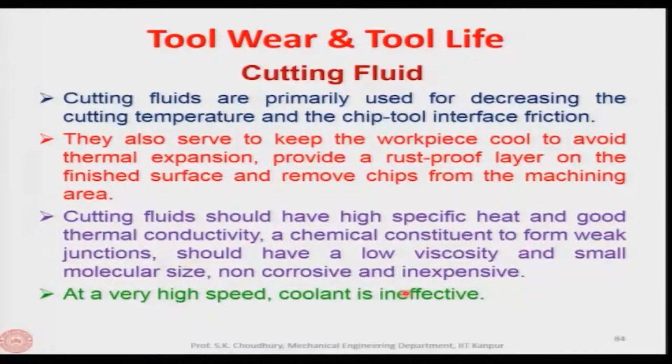Now, let us see the effect of the cutting fluid. Cutting fluids are primarily used for decreasing the cutting temperature and the chip-tool interface friction. So, there are two functions of the cutting fluid: to decrease the temperature and to decrease the friction between the chip and the rake face of the tool. They also serve to keep the workpiece cool to avoid thermal expansion, provide a rust proof layer on the finished surface and remove chips from the machining area. These are known. Cutting fluid should have high specific heat and good thermal conductivity.